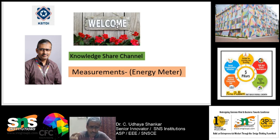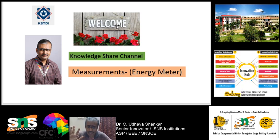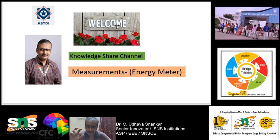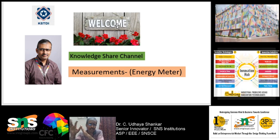From this we can understand what an energy meter is. An energy meter is nothing but a watt meter. You will have a watt meter, and along with that a time duration measurement of this power, how much time duration this particular power has been connected. A time duration monitoring meter will be along with the watt meter. So, an energy meter is a combination of a watt meter along with the duration for which this particular power has been connected. That is called an energy meter.